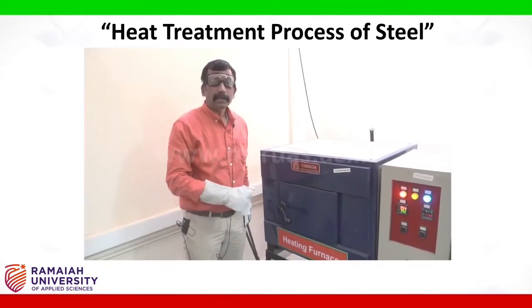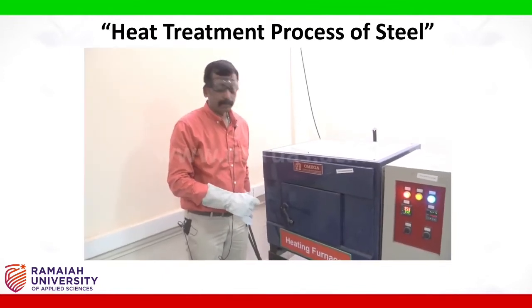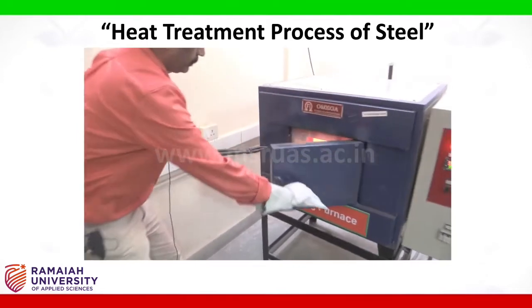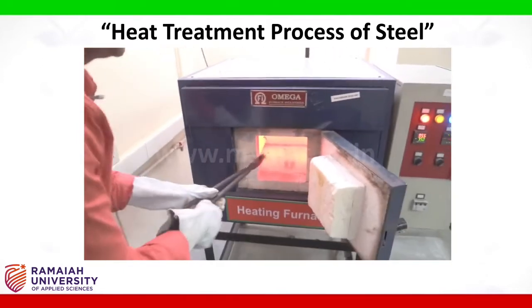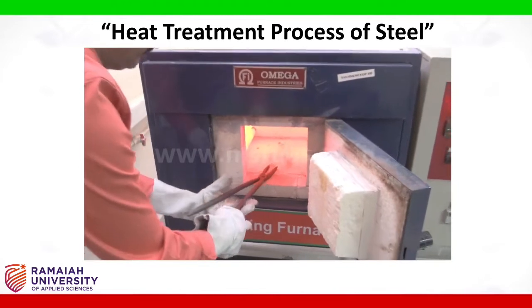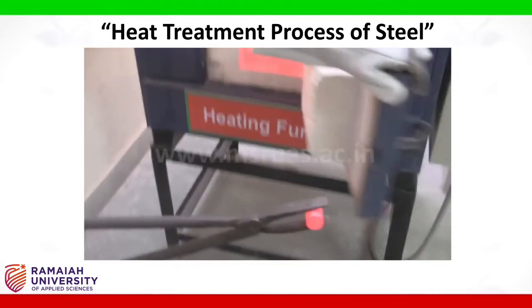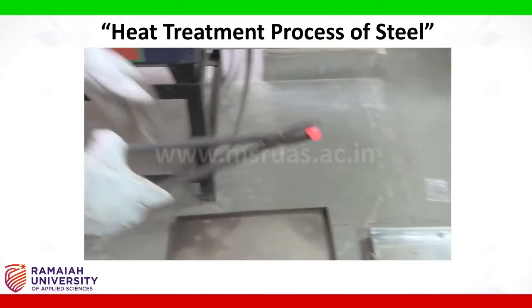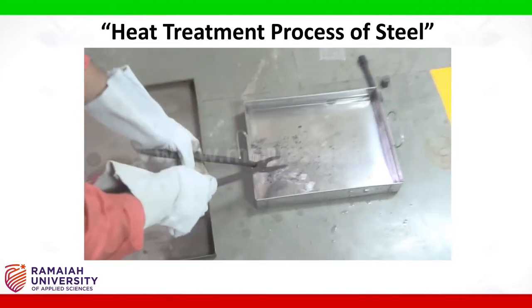Now I'll take the third set of samples to carry out the tempering process. First the sample for hardness and microstructure. First I'll quench it in water.